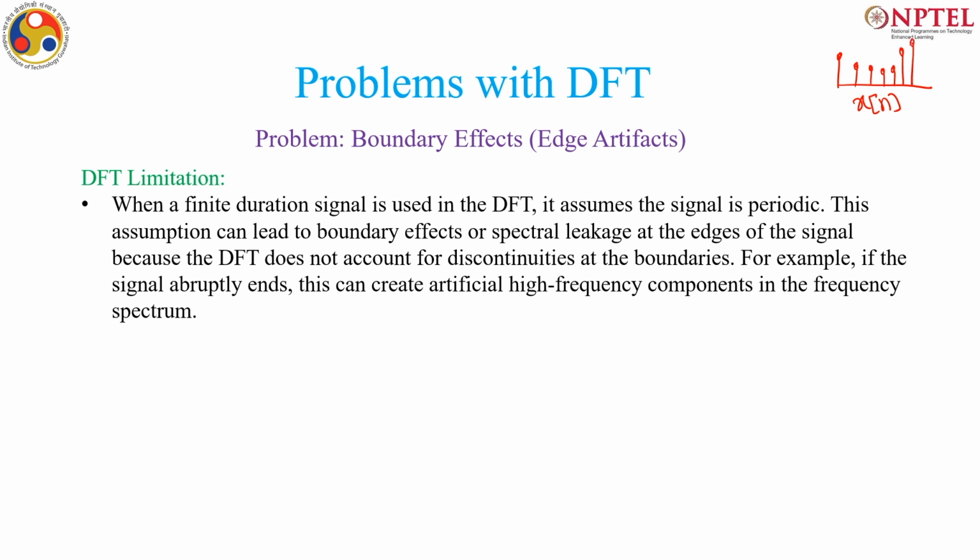So, say if this is my signal, let us say I have 8 points. Now, what will happen is, let me use a different color, and this will be repeated. So, this comes here. Similarly, here this tall value will come, and it is assumed that this is going up to infinity in both directions. So, this sudden change, these are called the boundary effects, and this will introduce additional frequencies which are inherently not